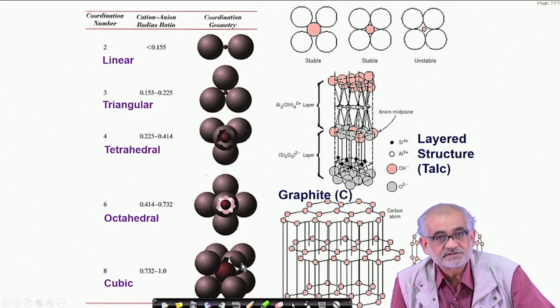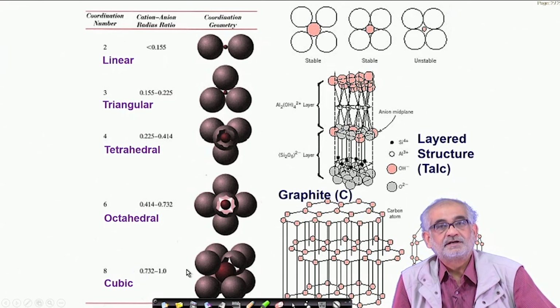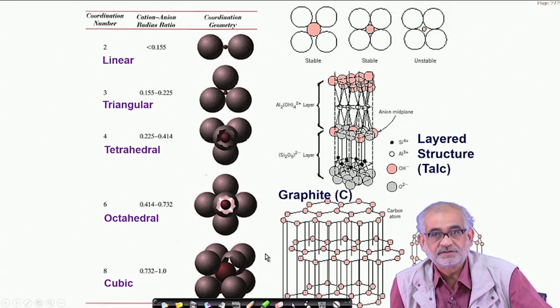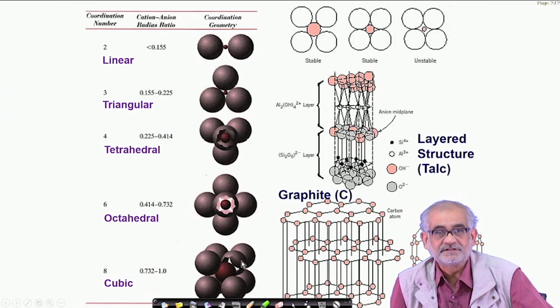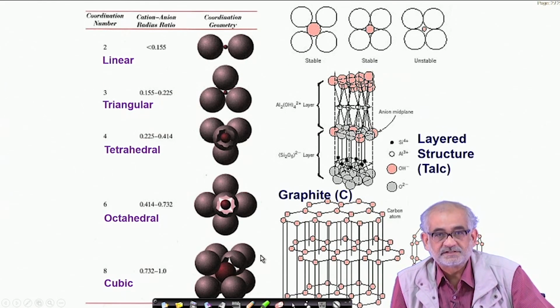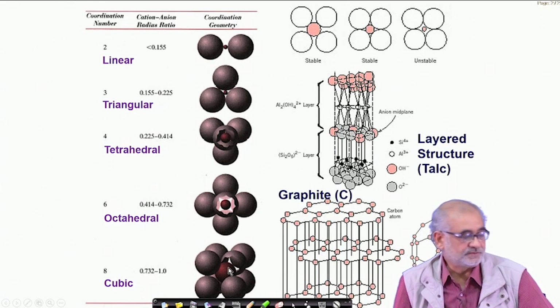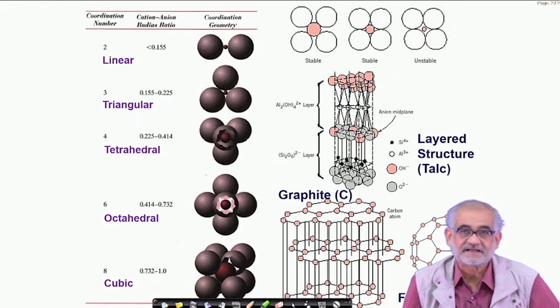And the most efficient packing, which I already mentioned, is manifested in the form of face-centered cubic and hexagonal close packed. They are possible only when you have similar sizes. So this is going to be possible only for elemental crystals of only one single size of species, and the maximum possible size difference there is basically none, they are of the same size, so the ratio is 1, and only in that situation can we have the largest packing density.